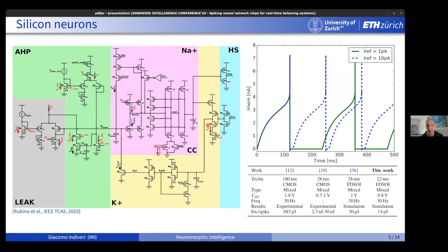And if you have a particular neural network that you think could be used to do a CPG, or to do sensory processing or motor control, we can actually connect these neurons together through synapses, through different nonlinear properties like short-term depression or spike frequency adaptation, and implement some computation.